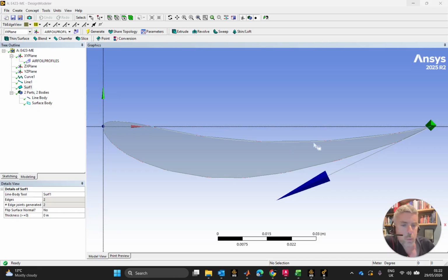Now, whenever we're changing the geometry, you have to be very careful, because after it's meshed, the meshing elements are arranged in a very particular manner around the airfoil. So it's not just a matter of mesh size, it's also a matter of mesh fitting, which is a function of the orthogonality and the skewness and all of these. Once that's resolved and we have a nice mesh made, all it takes is a small little jink in the geometry, and it'll throw the mesh completely off.